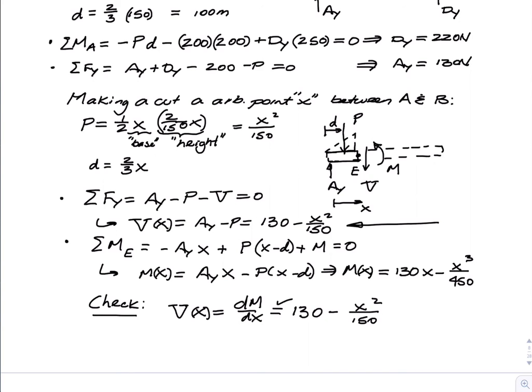So this is just to make the point that we can get them by equilibrium, by directly using a free body diagram and writing down our equilibrium equations, or we can look at the relationship that we also found from equilibrium in general. And the equilibrium relationship there is that V, the shear force, is equal to the derivative of the bending moment with respect to x.